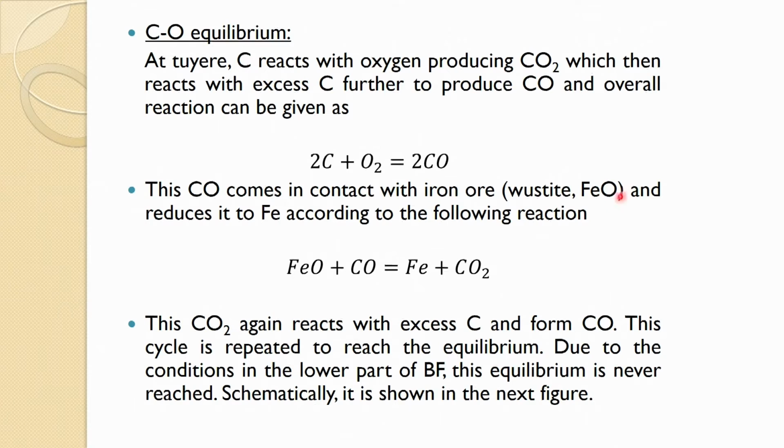As you remember, we mentioned that at the formation of the cohesive zone, melting of the ore and gangue starts. It makes a low eutectic solid, so it starts melting at the upper boundary of the cohesive zone, and at the lower boundary of the cohesive zone it becomes liquid.